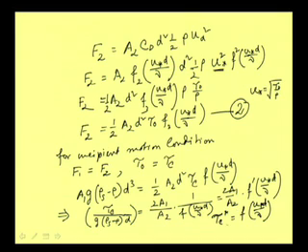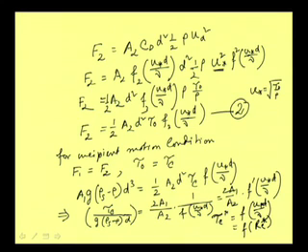So, this can be written as a function of r c star. This r c star is called the Shear Reynolds number. So, this tau c star, which is related to the critical shear stress, can be expressed as a function of the Shear Reynolds number R e star.